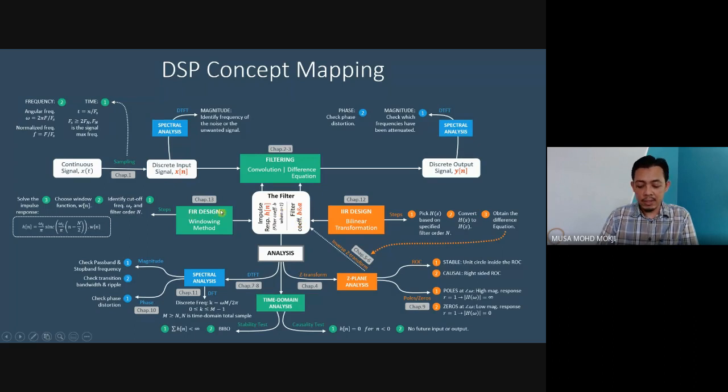For FIR design, the filter coefficient A is fixed, equal to 1, so we don't have to compute or find that. But for B, we will have some values for the coefficient B. The objective of this design is the output, and our expected output is the coefficient B. This coefficient B is actually equal to the impulse response for FIR.